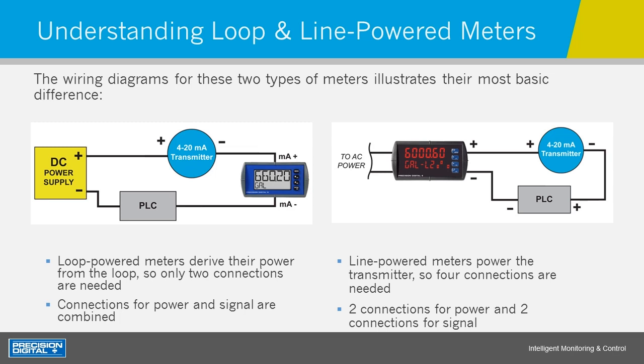Now, Frank, I know that you also asked a question about voltage drops, so let me explain what I meant there. I had mentioned that I had a 24 volt supply here. Every 2-wire device in this loop is going to have to drop a little voltage in order to have the power it needs to run. In the case of our loop leader, we've designed it to have a very low voltage drop of 1.5 volts. So I've got 24 volts to work with, and my loop leader is only going to drop 1.5.